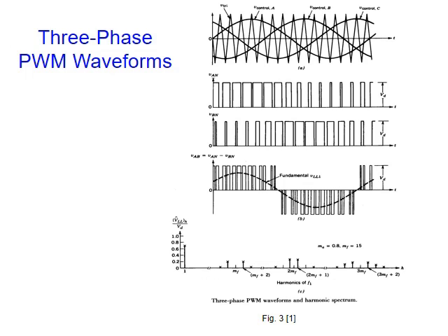Now for the pulse width modulation inverter, as you can see here, we will have sinusoidal control voltages for A, for B, for C. And since the control has 120 degree phase shift between them, the output is expected to have 120 degrees between them. If I take 2 legs, VAN and VBN, VAB is the difference between them. Similar to the discussion we did before in